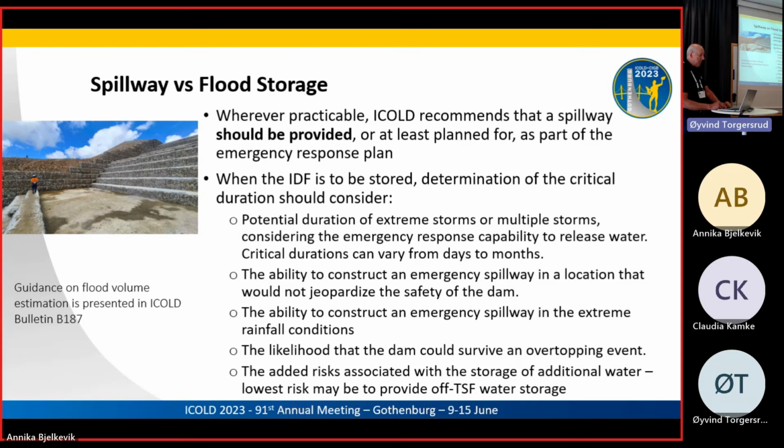Some dams could survive an overtopping event. I was interested yesterday to see the Norwegian method of riprap, where they had riprap on both sides of the dam. Whether that was designed for overtopping, I'm not sure, but some dams could survive overtopping. I'll show you some good ones in a minute. But the important thing to me is the added risk associated with storage of water that we'd really like to avoid. And so the ideal solution, and there are some cases I've been involved with, is to have an off-dam storage.